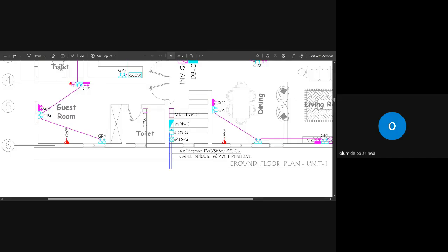Are we there with me? Now, I said, you know that your cable will come out of the ground floor. I said, you know, our excavation is 1 meter. So you now say 1 meter, shoot out of the ground by 1 meter. It will now go up into the building by 1 meter plus your 0.23 because of the wall. Are we noting it down?